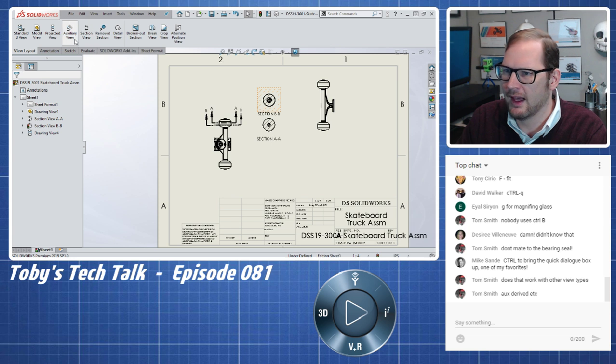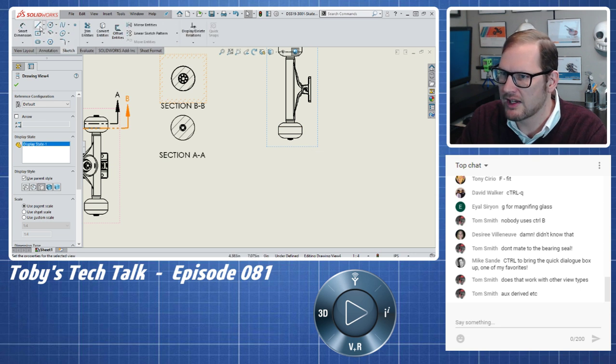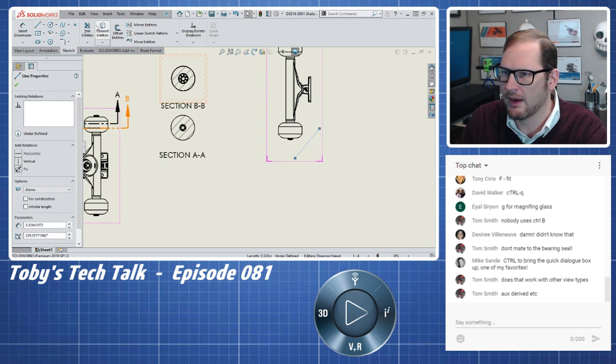Let's try it with maybe an auxiliary view. Probably the same with an auxiliary view, but let's just try it anyway. So I'm going to jump in here and just make a sketched line at an angle so I can dump in an auxiliary view there. Take that guy, and then I'm going to go here to my view layout, auxiliary view.